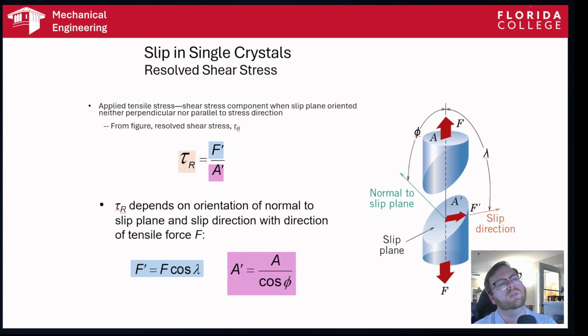Okay, so when we look at single crystals, we can actually identify our slip planes after fracture. So remember the aluminum test strip that we were looking at last lesson. It wanted to slip along a certain diagonal. There are other reasons why this happened as well, but there is a convenient slip direction associated with that also has a hand in making it neck and break in that specific direction or orientation.